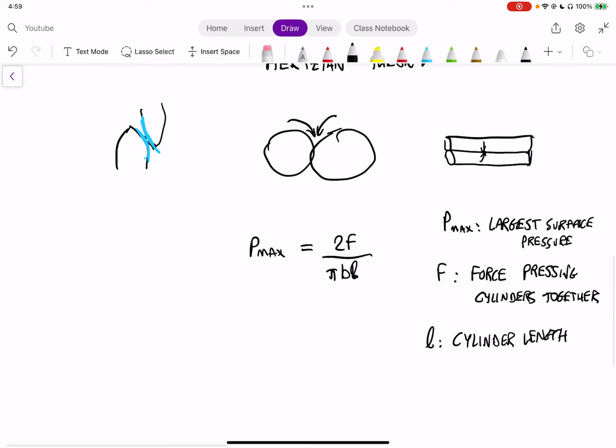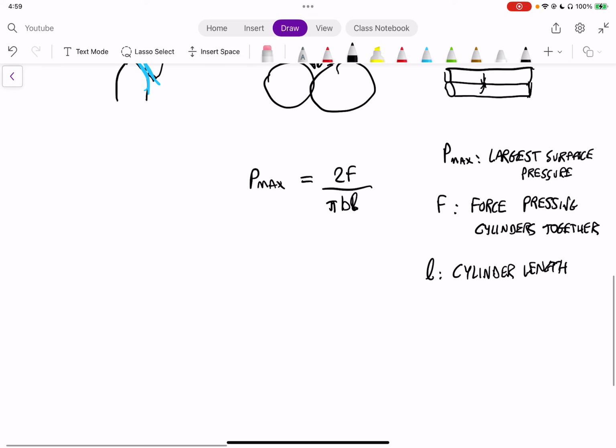Okay, so in this case, basically the width. And then b is called the half width, and it's not really a geometrical component. This is something that is developed more in Hertzian theory, but essentially it's a combination of Poisson's ratio and modulus of elasticity to try and get a value for a half width, which doesn't really stand for that, but gets us a value of Cp, which is the coefficient of elasticity, essentially.